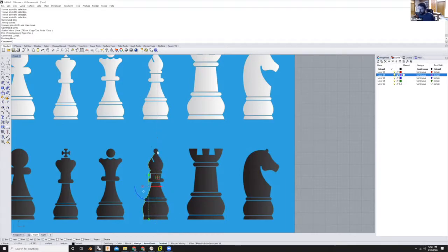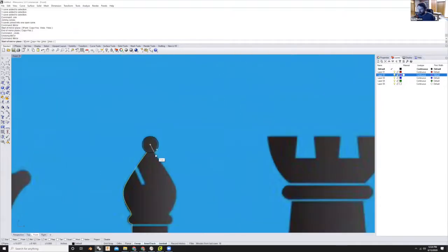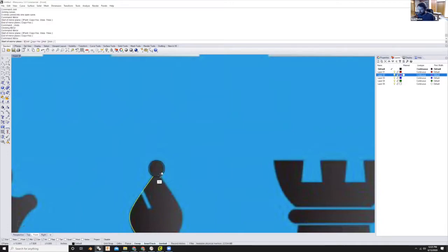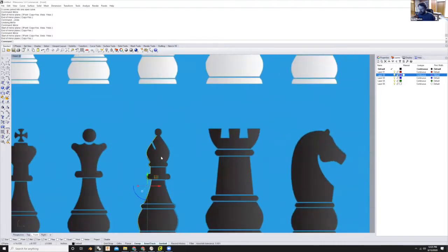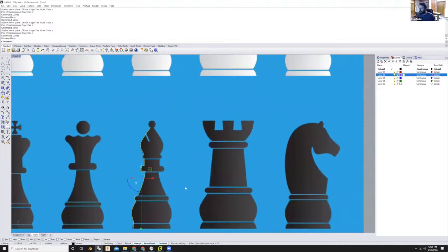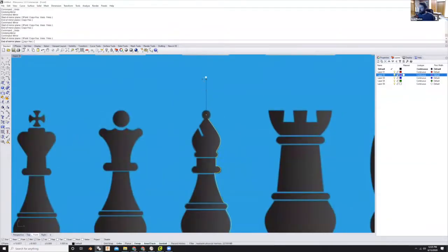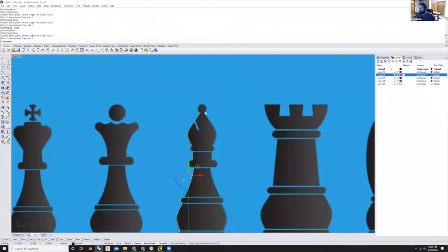Oops. Let me do that again. Hold shift and snap to this plane here. Another way to do it without holding shift is to turn ortho mode on. And so I can turn ortho on, find the center, and then it will reflect upon that center.